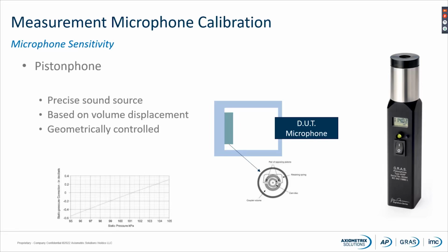It's geometrically, we have to make a geometrical control of it, because depending on the atmospheric pressure, we have to compensate for the atmospheric pressure. So the level inside the chamber will be a little bit more or a little bit less, depending on the atmospheric pressure. But it's a very linear curve, so it's rather simple to do the corrections.